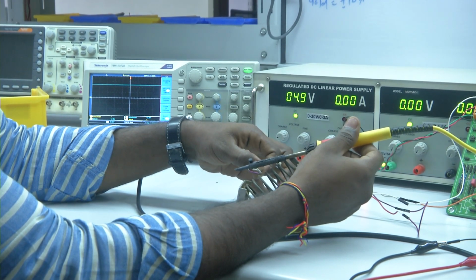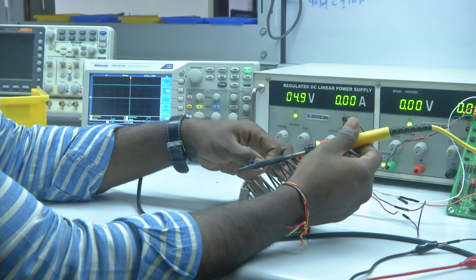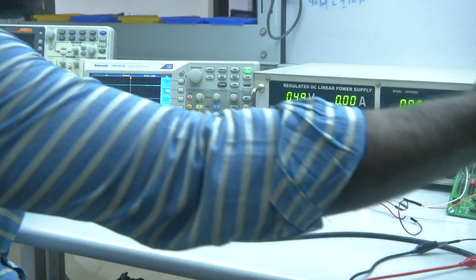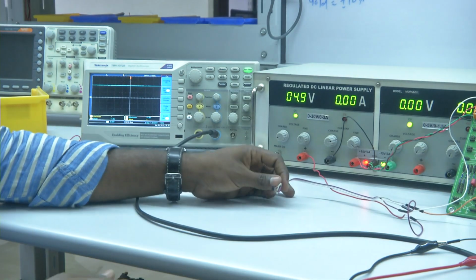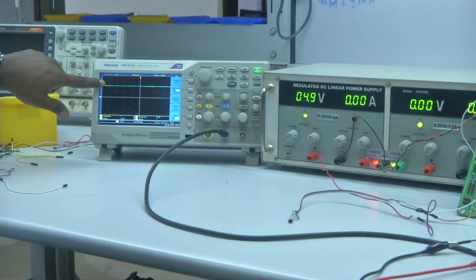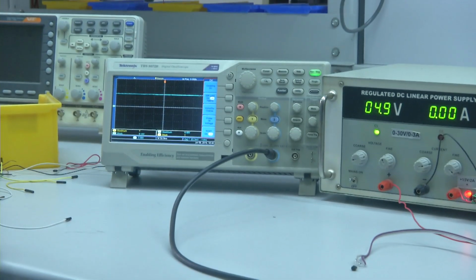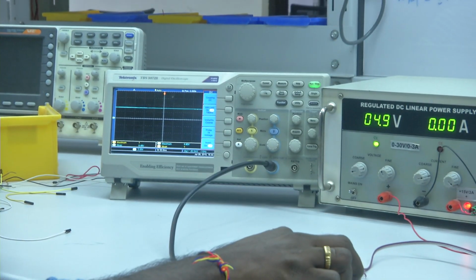So, the heating station has heated to a little high temperature. The maximum voltage it is showing is 12 volts, which means that, if we consider the gain of 10, it is at 120 degrees centigrade. Now I have removed the connection, and it will slowly come down because of convective cooling, to room temperature.